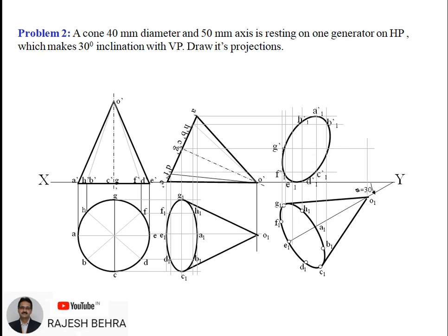Now see here, this complete ellipse, or we'll say a curvature. If we see from here, C is the part or point which is coming nearer to the observer. So an arc passing through C will be visible. C is inside one, because if we draw from the extreme generator, see here, if we draw this extreme generator, C is the part which is coming inside.